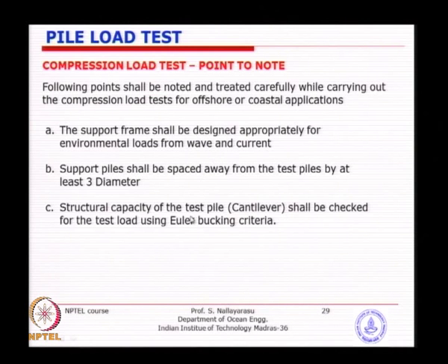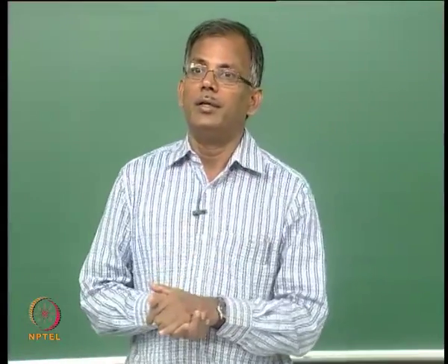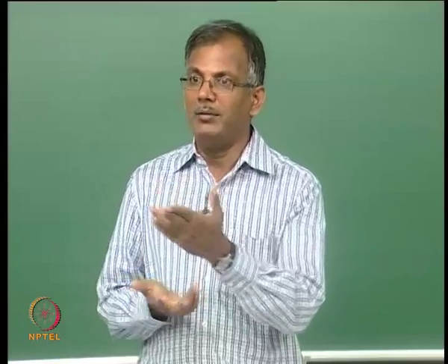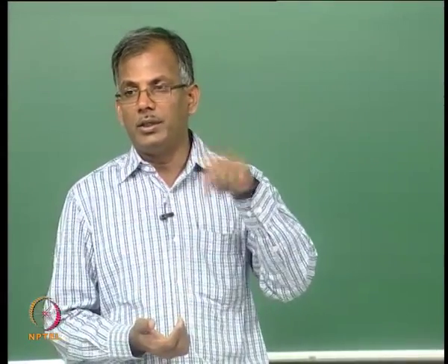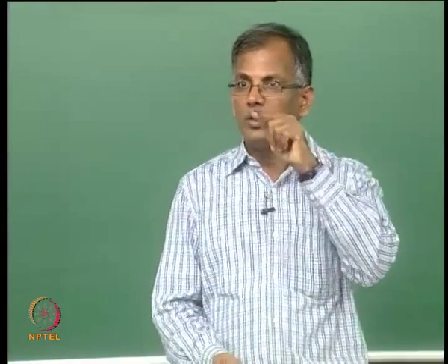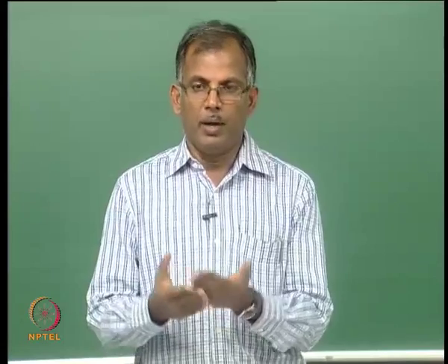Structural capacities of the test pile as well as the support piles need to be made sure to be adequate. Special care must be given to the test pile, because it is a cantilever, whereas the same pile when it is working in the actual structural system may not be a cantilever, it may be combined at the pile heads with other structures, whereas when you are doing testing it is a pure cantilever. You must remember the difference between the pile in a temporary condition, which is a cantilever, and a supported pile in the permanent condition.